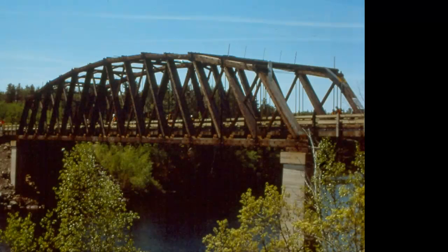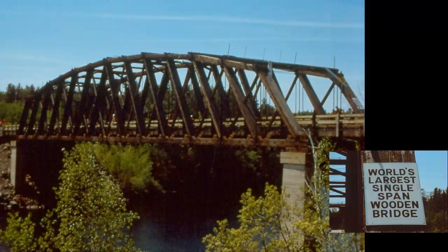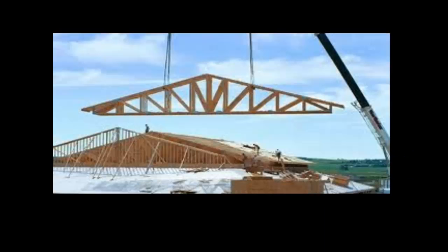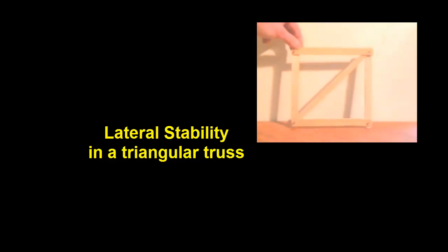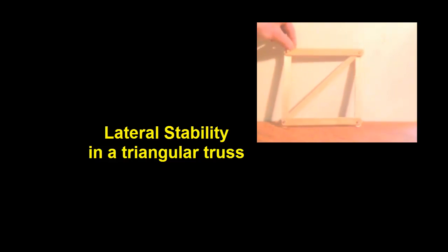The truss system has many more members than a beam, so it is more complex. All the members are pin-headed and are either in tension or compression, not in bending. So the internal forces are simpler. A critical condition for a truss is that all the members are joined to form triangles. If they formed a rectangle, the system is unstable, as evident in the popsicle stick model. If the diagonal is added to create two triangles, the truss becomes stable and acceptable.